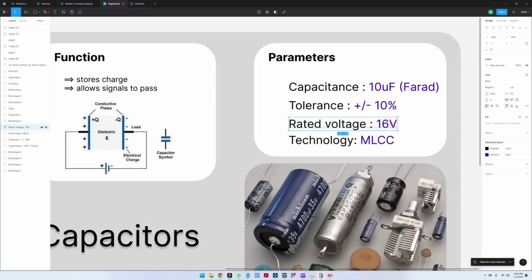So in this case, with a quite small rated voltage of 16 volts, do not try to go above 12.8 volts, because it would strain the capacitor a bit, and in time this would cause a failure. If you have a circuit that has an output voltage closer to 16 volts, it is better to use a 25 volt or a 50 volt rated capacitor for your application.